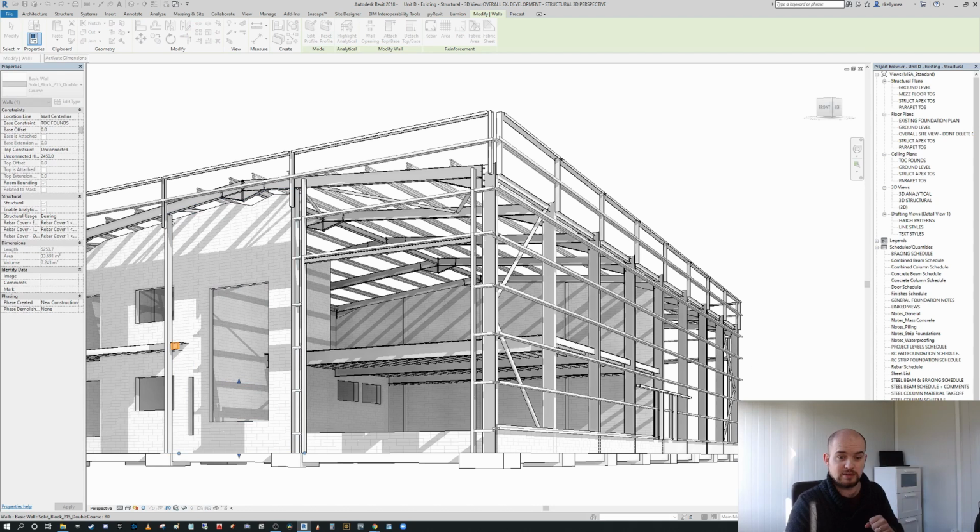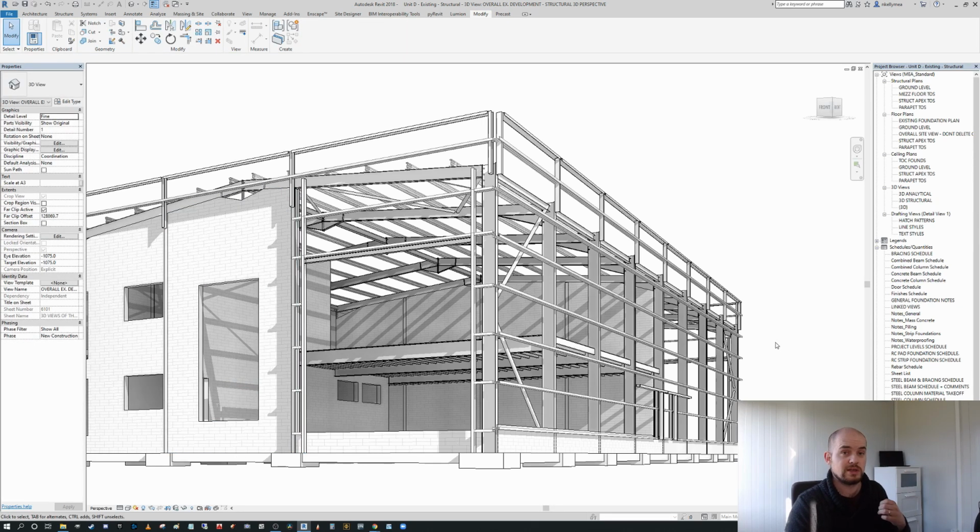And as you can see, it breaks things. And you don't always get that warning to notify you. Sometimes a change will happen and Revit will see it as a non-consequential change. That's because you had an element by face and you were working in a plane that was perpendicular to it, which means that you shouldn't have been able to select that element by face meaningfully. It just doesn't make sense, to be honest with you. So generally, I tend to leave that turned off.